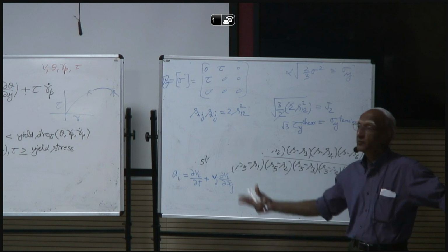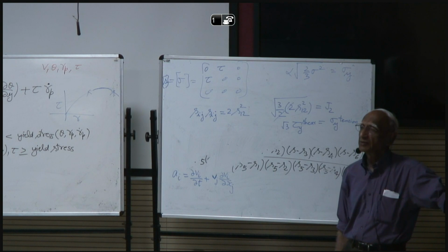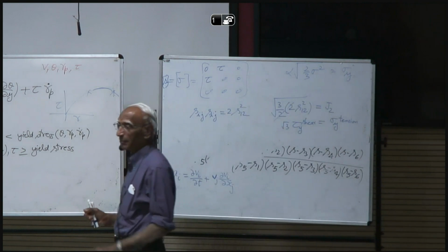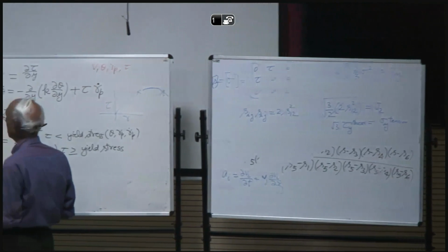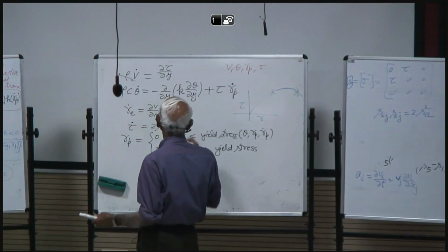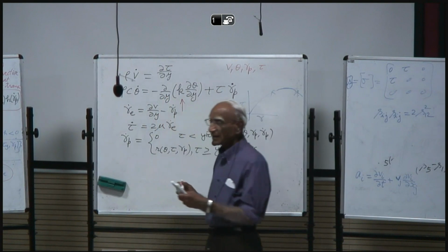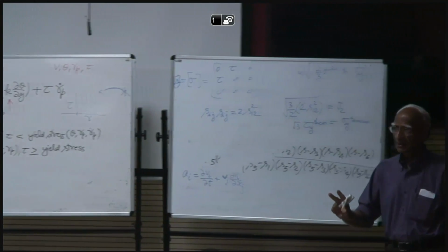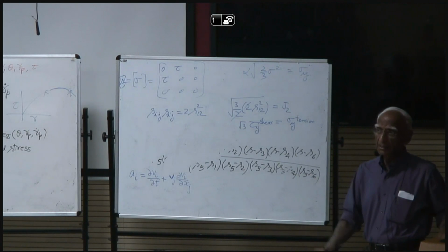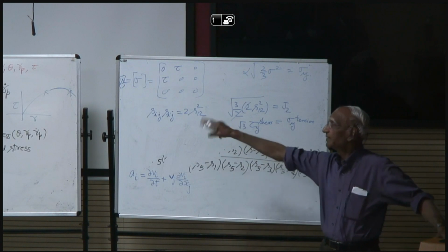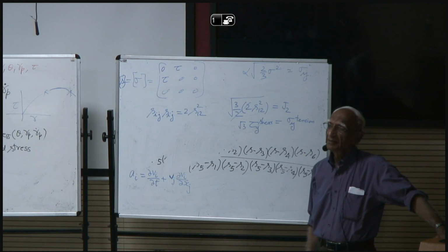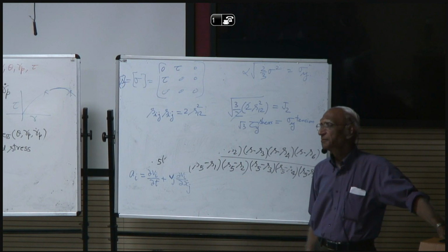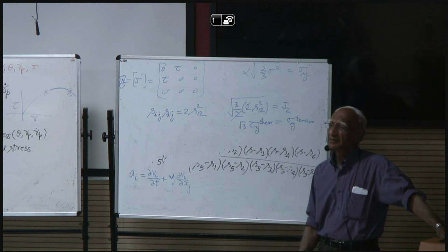You have to do numerical experiments to find out. I cannot tell you in advance. It generally depends upon thermal conductivity, because that is the only thing that introduces a length scale into the problem. But it's a very weak length scale. If you do not consider thermal conductivity and do not consider a strain gradient type theory, there is no length scale in the problem. So thermal conductivity is the only one in this case that helps, but it's a very weak dependence.